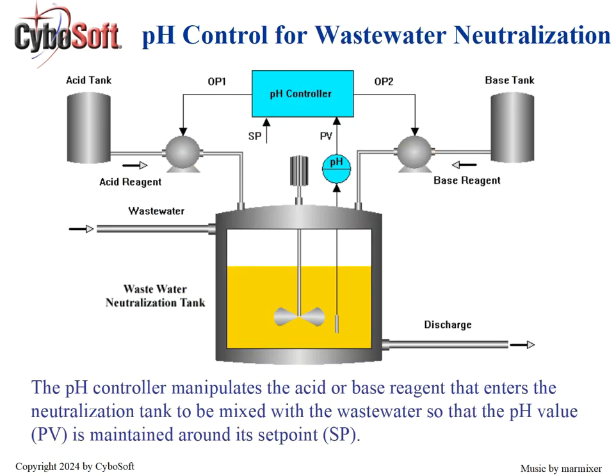This diagram shows a typical wastewater pH neutralization process. A pH controller regulates the flow of acid or caustic into the neutralization tank, where it mixes with the wastewater to maintain the pH around its set point.